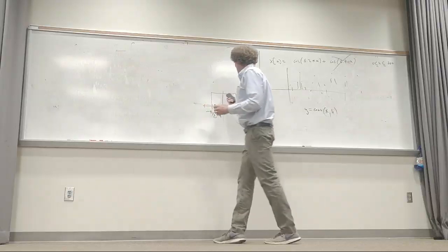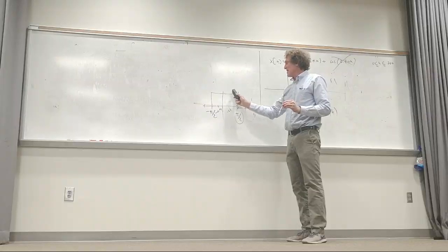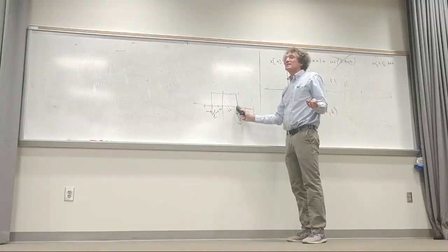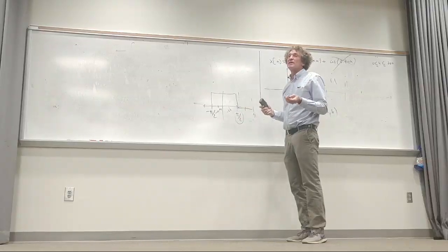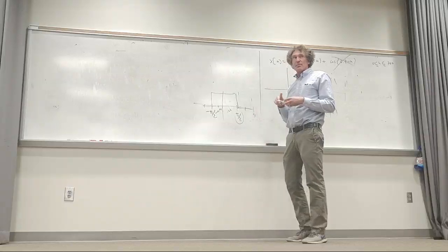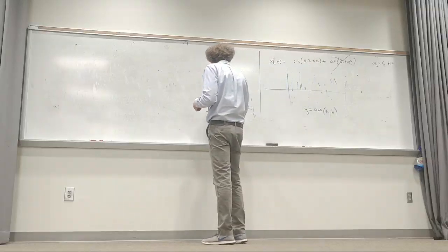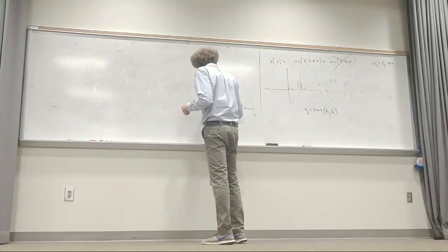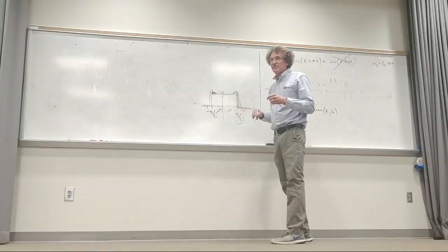But what's the dB reduction in what we tried to do right here? It's going from 0 dB to minus infinity dB instantly, right? It's got a roll-off greater than anything you can achieve. If you actually take that impulse response that we did, the truncated one, do the Z-transform and plot it, what you should get is something that's flat, there's an overshoot and it comes down, but the window gets rid of that, and it's basically like this. It's a very, very good filter. It does have a slope, but that's like 50 or 60 dB.